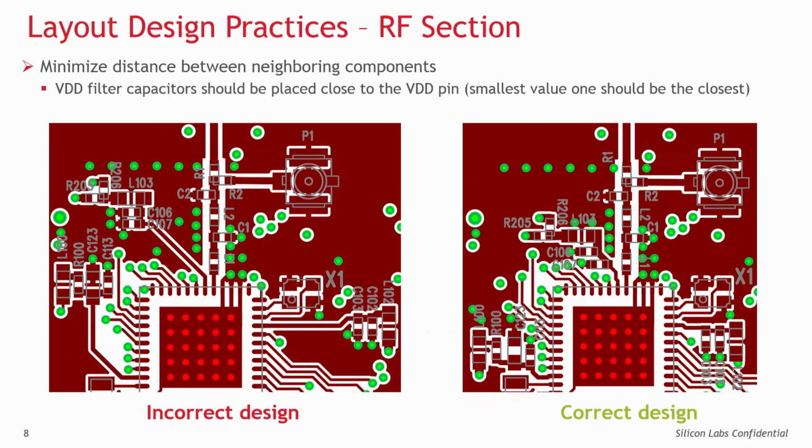The lowest value bypass capacitors filter on frequencies around the fundamental. This way they have to be placed close to the VDD pins and need good grounding with many close vias at the ground side. The capacitor with the value around 100 nanofarad filters the several tens of megahertz frequency range, thus the leaking clock spurs. Filtering these spurs is important as they can be upconverted inside the chip, causing unwanted spurs at several 10 MHz